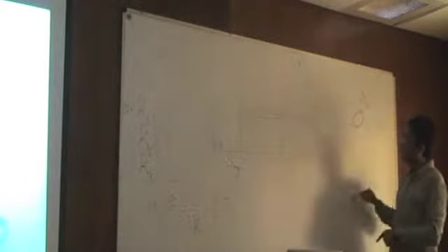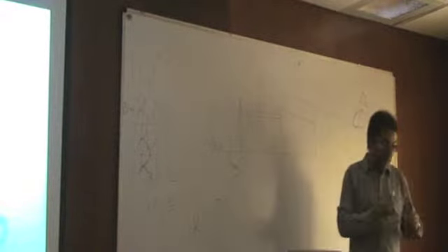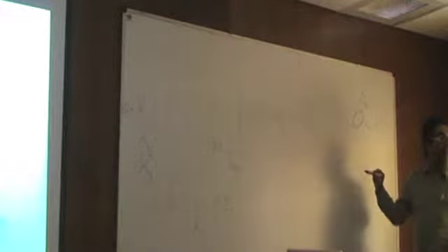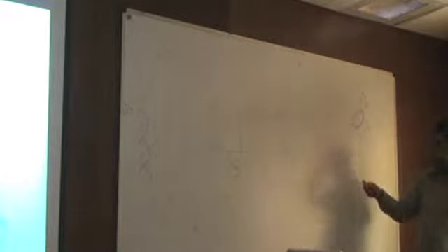But the geometry is changing, and the geometry information goes into this. So when this is flattening out, your I2, the moment of inertia about this x2 axis, is going to reduce, right? Because your moment of inertia I2 is defined as x3 squared dA integrated over the cross-sectional area, whatever that thin wall cross-section is.